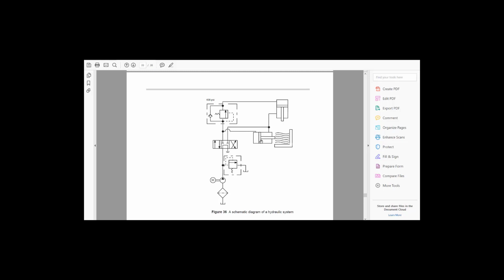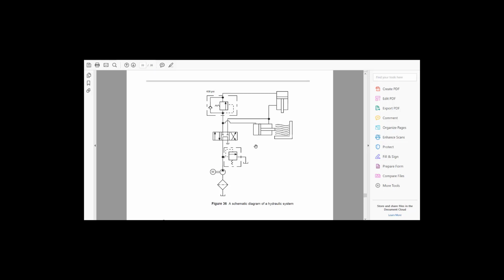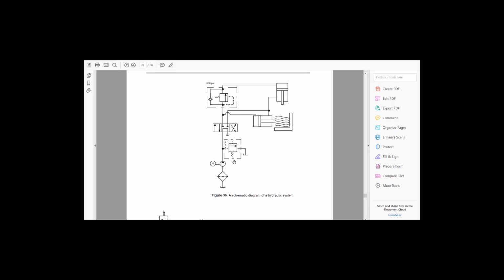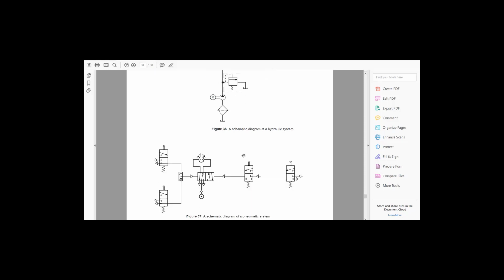It looks like in this example there is a cylinder that presses on the side of this storage, and once the pressure is reached on this clamp cylinder, then the press cylinder will come down. So all it does is tell me how the system operates for troubleshooting purposes.